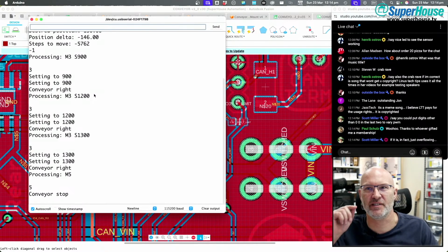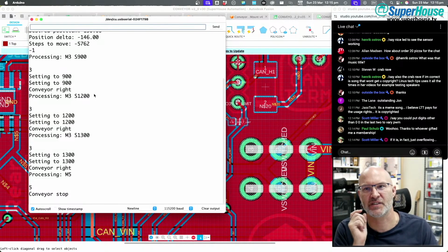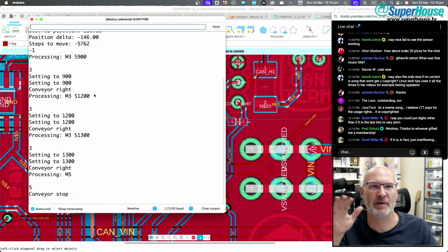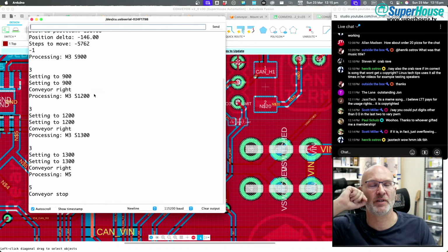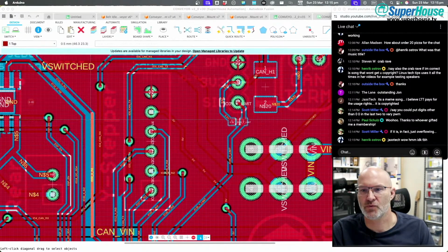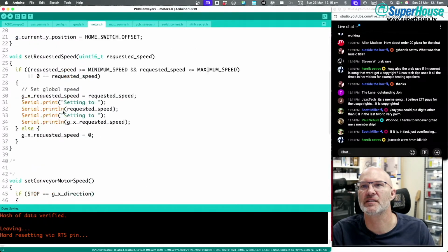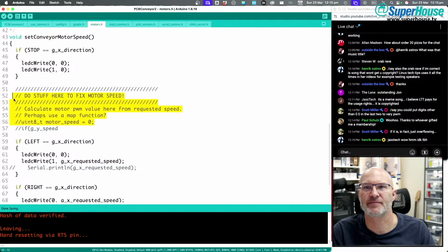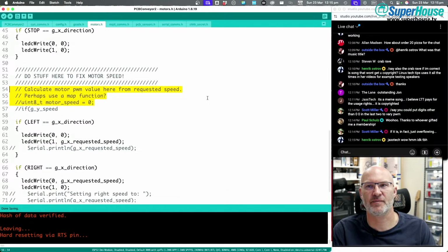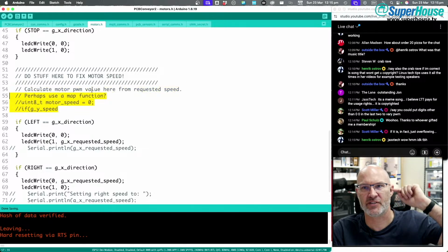What I need to do is make sure I have the correct motor. Because if I don't have the correct motor in there, then no amount of tuning is going to fix this. So I need a 120 RPM 12 volt motor in it. And then I can fix this and be able to give it a speed, and the actual PWM frequency should be fixed.